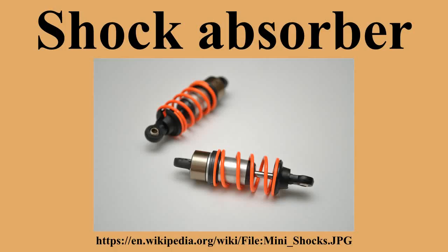Conventional shock absorbers can be combined with air suspension springs, an alternate way to achieve ride height control and self-leveling suspension. In electrorheological fluid dampers, an electric field changes the viscosity of the oil. This principle allows semi-active dampers application in automotive and various industries. Magnetic field variation: a magnetorheological damper changes its fluid characteristics through an electromagnet. The effect of a shock absorber at high frequencies is usually limited by using a compressible gas as the working fluid or mounting it with rubber bushings.